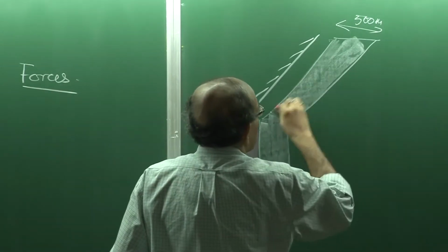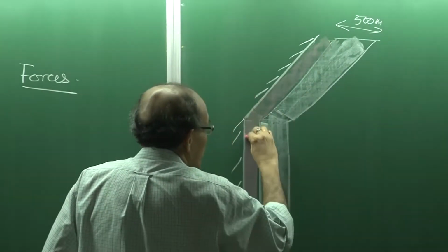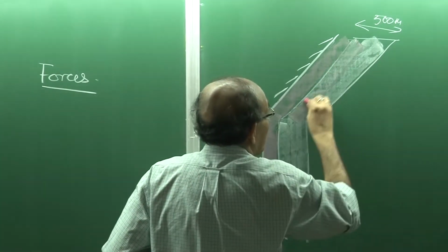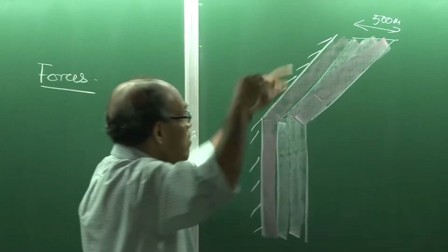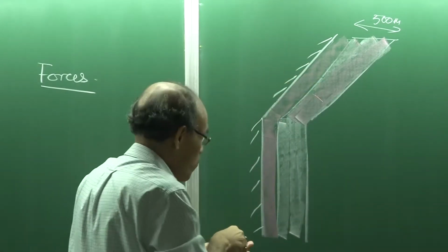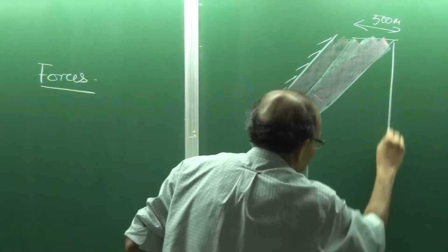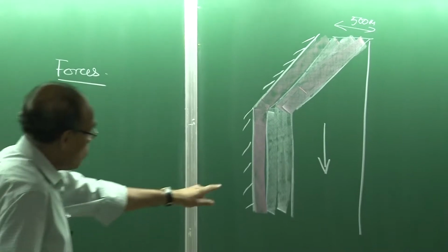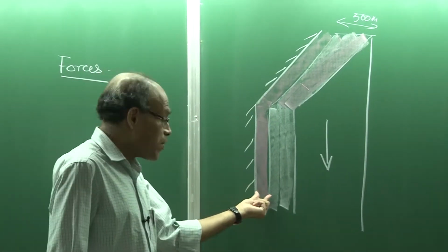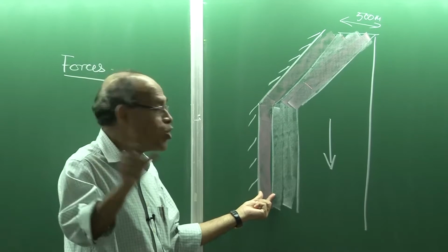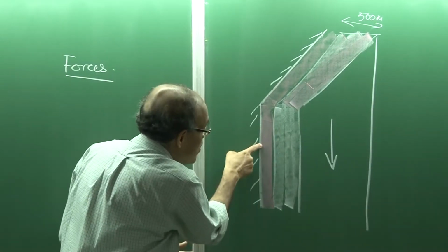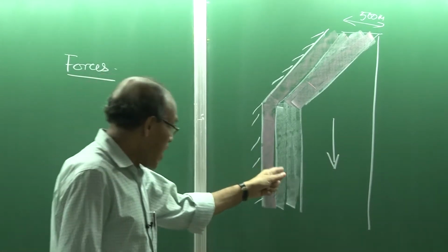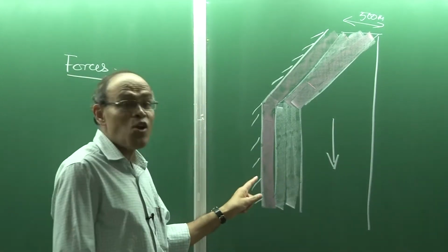So it is all over this area which is filled with liquid mold powder, and actually the mold powder is sprayed over the surface. So this is the top surface, and this is the direction in which the ingot or the casting is really drawn. So whatever is the pink shade here represents basically the mold powder or molten mold powder, which acts as a lubricant between the mold wall and the solidifying casting. This is used just so that the solidifying metal does not stick with the copper mold.